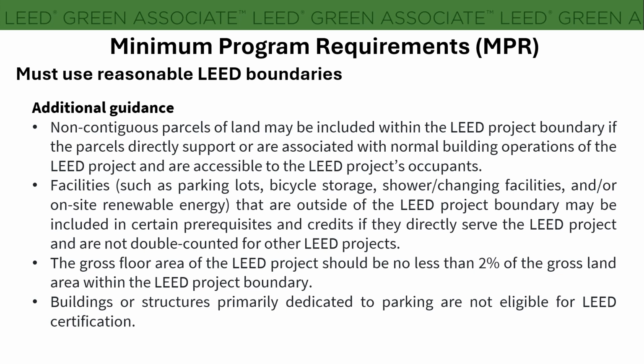Then facilities outside the LEED boundaries can also be considered if they actually serve to achieve the prerequisites or credits for the project. And one case is important: it should not be double counted for other LEED projects. Then the gross floor area of the LEED project should not be less than 2% of the gross land area within the LEED project boundary, and buildings or structures primarily dedicated to parking are not eligible for LEED certification.